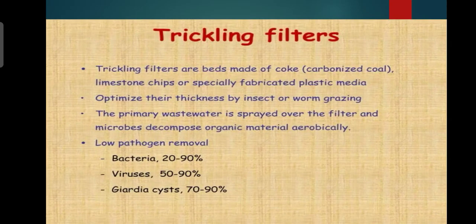Trickling filters. Trickling filters are beds made of coke, limestone chips, or specially fabricated plastic media. Their thickness is optimized by insect or worm grazing. The primary wastewater is sprayed over the filter, and microbes decompose organic material aerobically. Low pathogen removal.